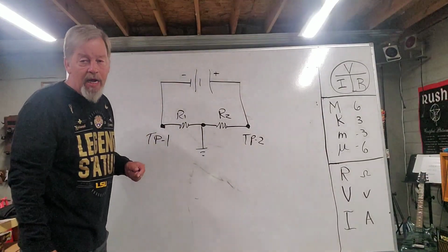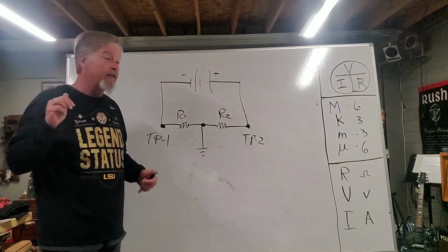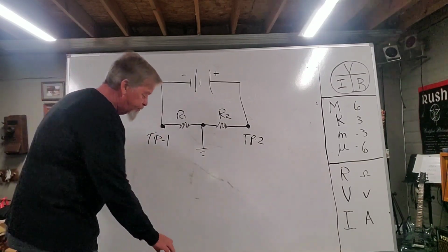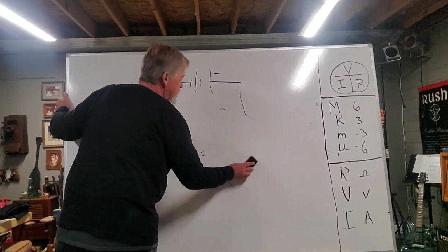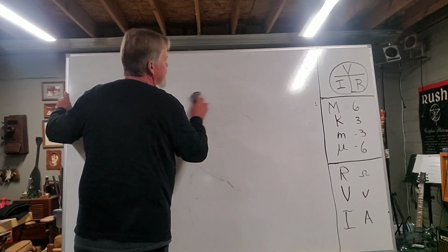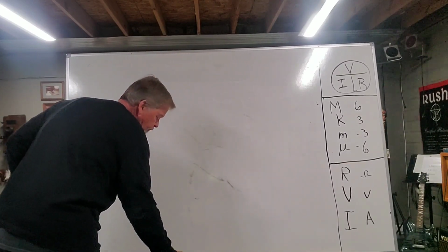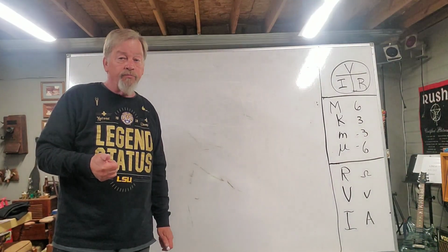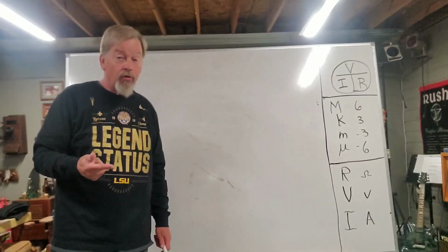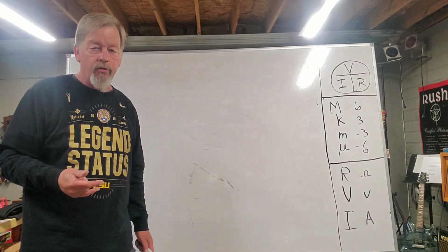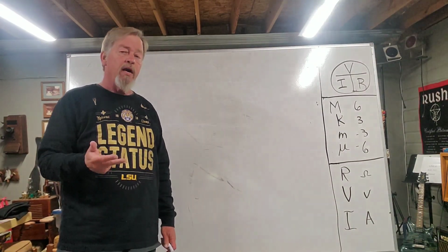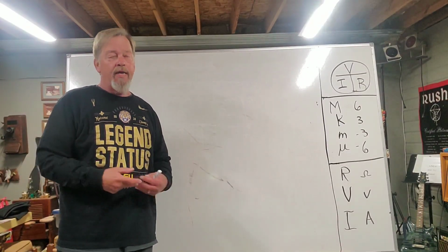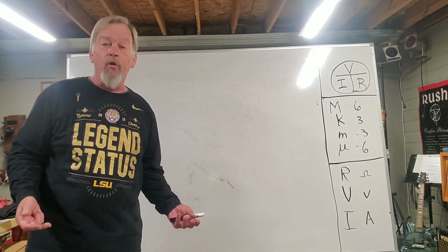Okay, so what's the difference between positive voltage and negative voltage? Well, I'll tell you this. They'll both shock you the same amount. It doesn't matter. Look here. In every voltage measurement, there are two indications. There's an indication of potential, and that's the number that comes up on the screen, and then polarity. Polarity is the negative and positiveness of that voltage, in reference to the measurement from ground.